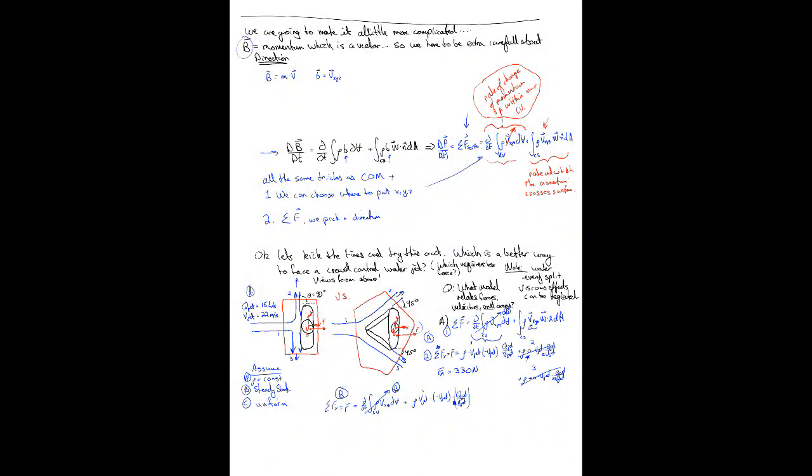All right, now we have to take care of our other entrances and exits. So let's do 2. And we're going to see we get something different now. We get rho times the x component of our momentum for exit 2, which is the top exit, which is leaving at 45 degrees relative to the horizontal. Our velocity there is v jet, but the x component is multiplied by the cosine of 45 degrees.